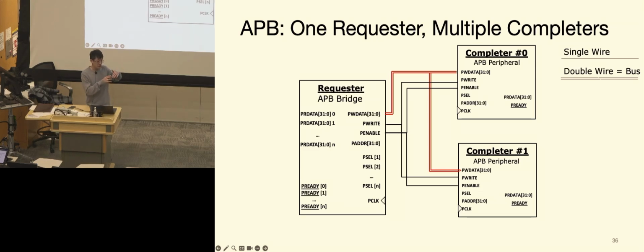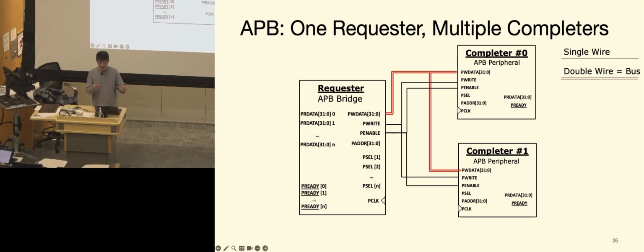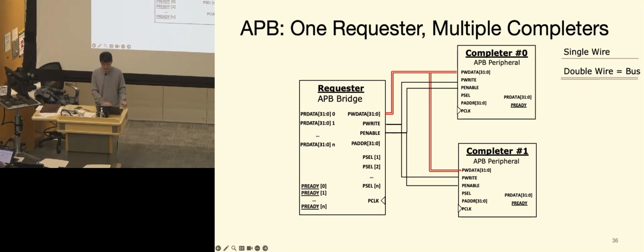We connect this to all the peripherals so that every peripheral is synchronized with the same data phase stage, so that there are no collisions. It's easier for the master to control the data flow. And of course, the address goes everywhere. All the peripherals have the same access to the address, so that they know if it's their turn to be called up.